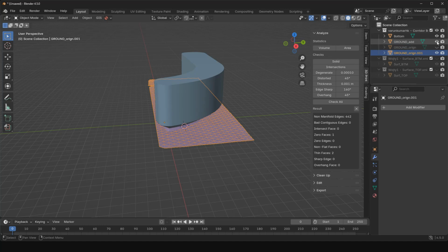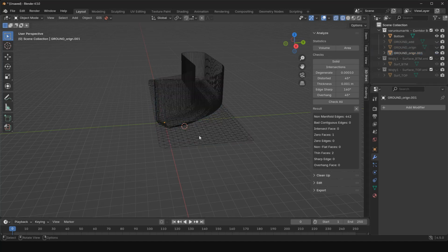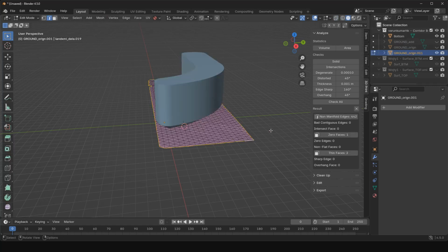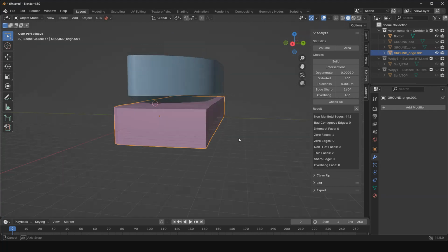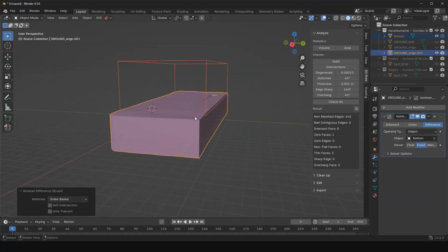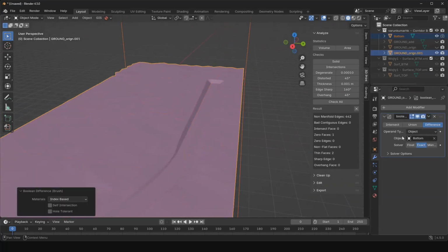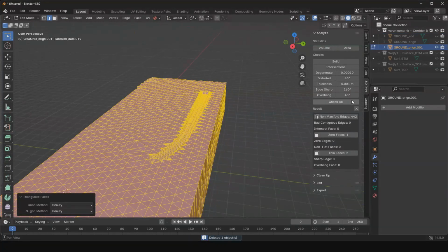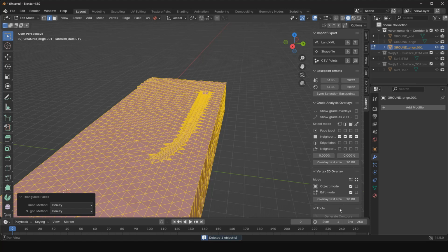and we're going to need to do the same thing with our, let's delete, duplicate the original. So trying to select that. We're going to do the same thing as we did previously, where we make it a solid, and we're going to cut into it using Control minus from the Bool Tool add-on, and we arrive at a perfect surface once again.